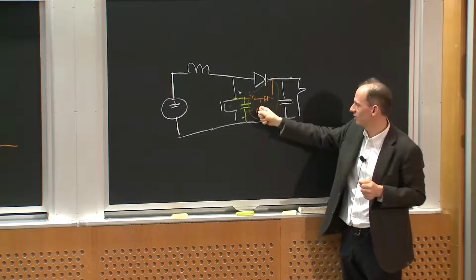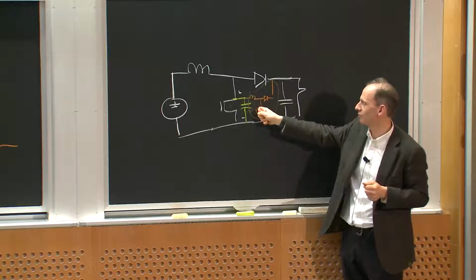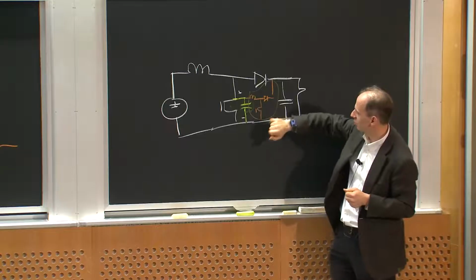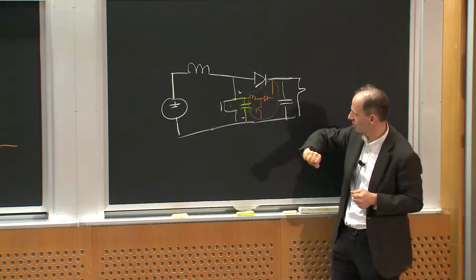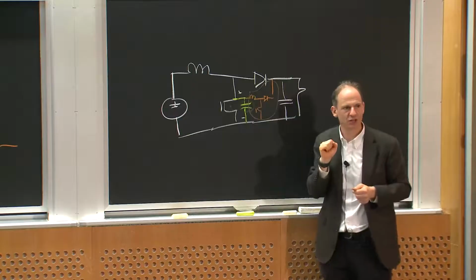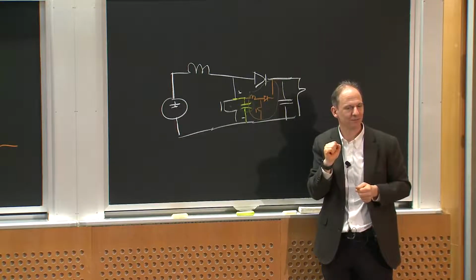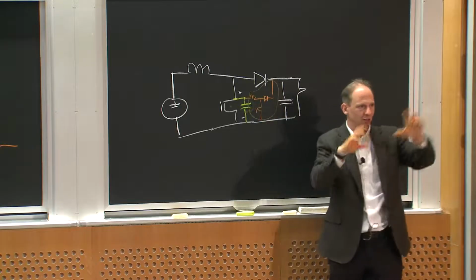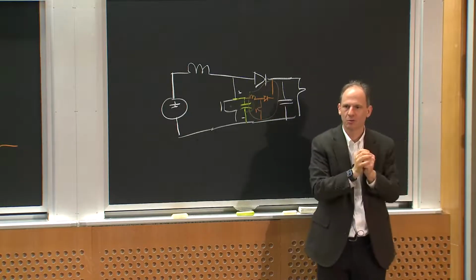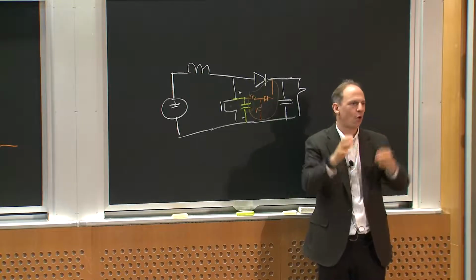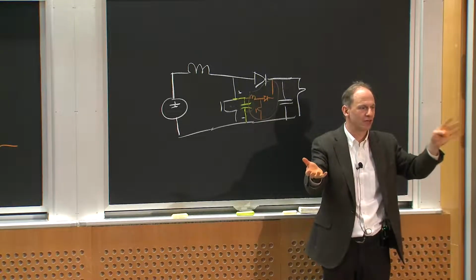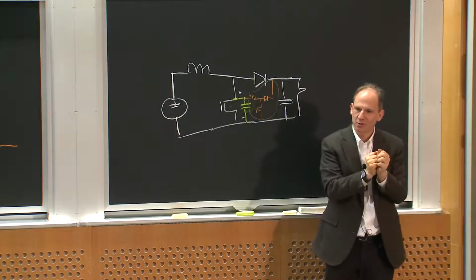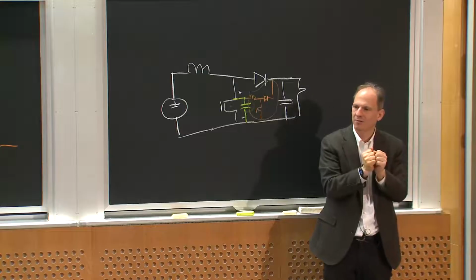But still, this device is turning on and off at zero voltage. It's got a very high peak pulse power. But nonetheless, as long as I use this orange circuit at the opportune time, I can run the rest of the converter just like a normal PWM converter. So I'm adding an auxiliary circuit comprising the green and orange circuit to let me operate the regular circuit just like a normal PWM converter. That's a whole category of soft switching converters: how do I augment my normal PWM design so that it also gives me soft switching and I can get either a higher efficiency or higher frequency?